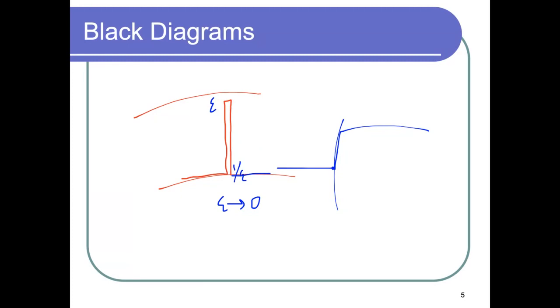So the Laplace transform of the impulse is 1, and the Laplace transform of the step is 1 over s. That's why when we study the impulse response, we take the inverse of G(s) directly. For the step response, we take the inverse Laplace transform of G(s) over s, because we're multiplying by a step input. So that's the difference between the two.